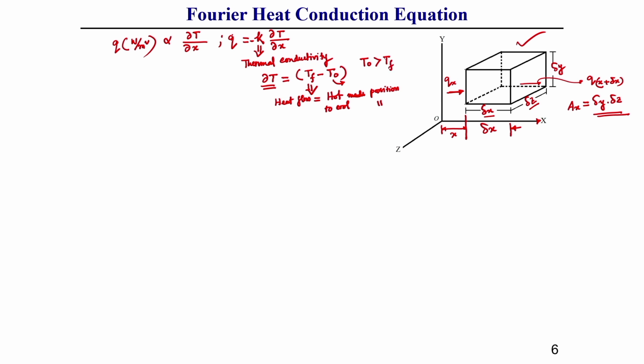but whatever heat flux is generally flowing is a positive value, because heat is generally flowing along the positive x direction. So, this is a positive value. That is why, to make Q a positive quantity, this negative sign is coming, because this delta T is already negative. To make this negative thing positive, we need to put another negative term here, then this Q will become positive. This you should keep in mind.